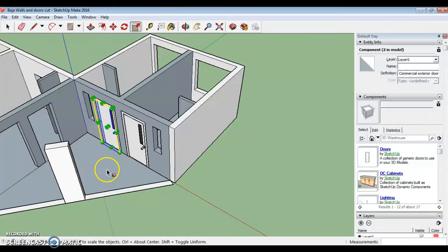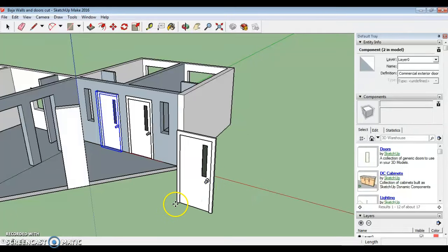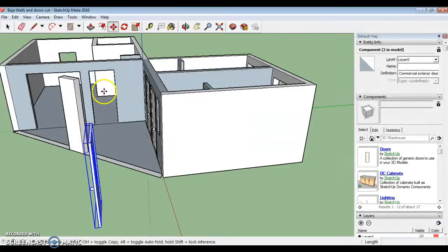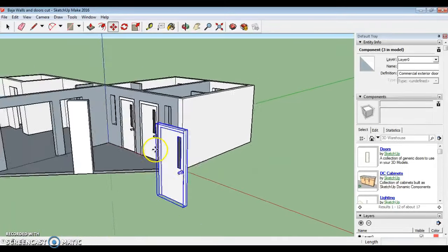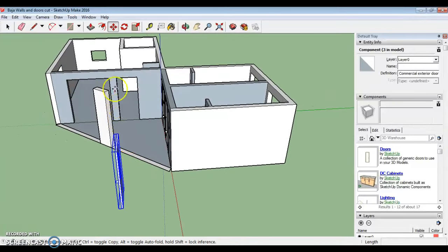And finally, we just want to show you how to rotate stuff in the opposite orientation. So if we just create a new door again real quick right here, you can see if we wanted to install the door, say in the opening back here, it's facing the wrong direction, right? So we want to show you how to rotate that. In this example, it's like rotating like a helicopter blade.